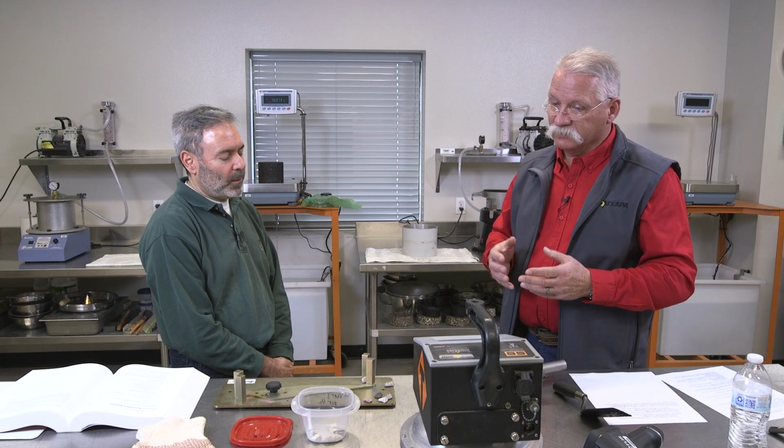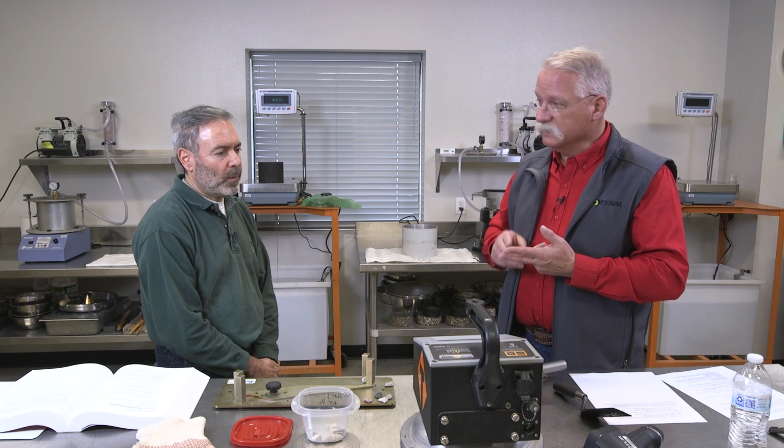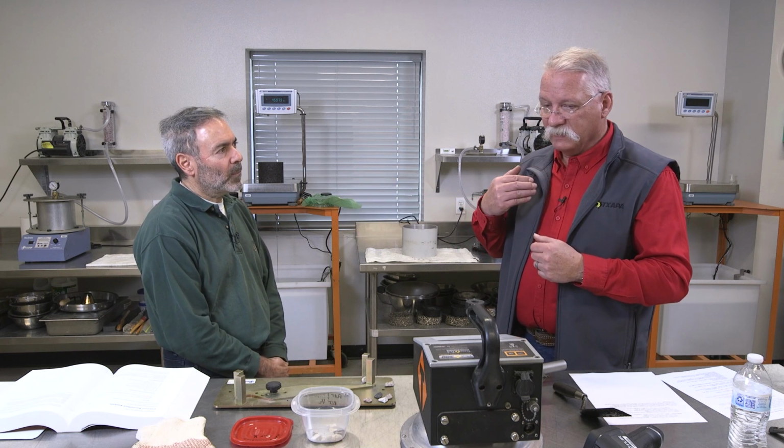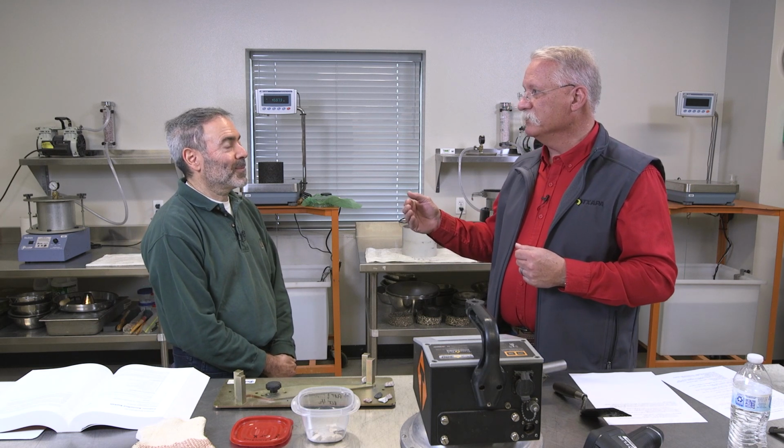Again, what we're trying to measure is material variability. That is the goal. We don't want to measure sampling variability. We don't want to measure our testing variability, even though there's some there. We'll never be perfect. You run a mix perfect, you run a sample perfect, I run a sample perfect. If we get exactly the same number, then we should be suspect, because that rarely ever happens.